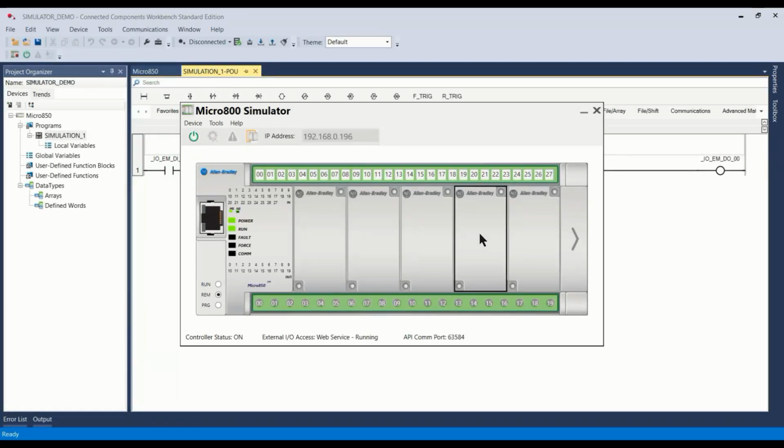Micrologix, all PLCs, they have an internal watchdog, and what it does is, after the first scan of any project, it looks at it and says, okay, that took me X number of seconds, and it adds some milliseconds to it. Basically, this is super simplified, but it then checks every time it scans through that the program was satisfied within reason of that watchdog, and if it doesn't, something has gone wrong and it will create an error. That's just to bring it to your attention that, hey, something's not gone right here. We've done the scan and it's not meeting our scan time. Something's not right, so check it.